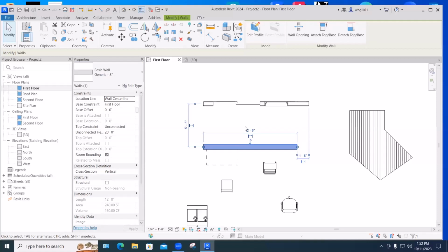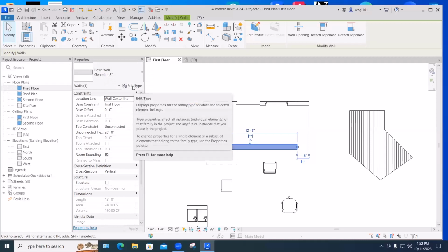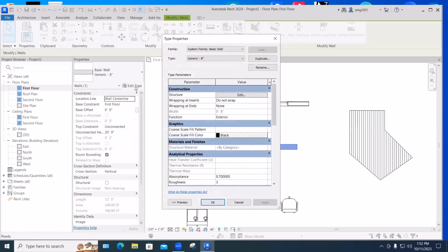And so here's a process we're going to do over and over and over again for the rest of the time that you're using Revit. We're going to pick something that's close to what we want to end up with, and we're going to do 2 things. We're going to say edit this type, edit the dimensions of this geometry, and we're going to duplicate it. Edit type, duplicate, edit type, duplicate, again and again and again. So we're going to take pretty much everything about it. We're going to change its name to 11-inch, and we're going to change its width to 11-inch.